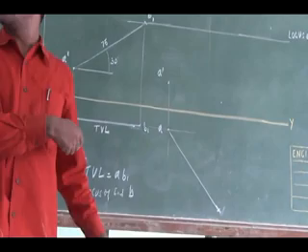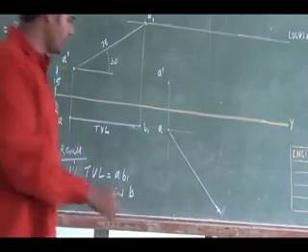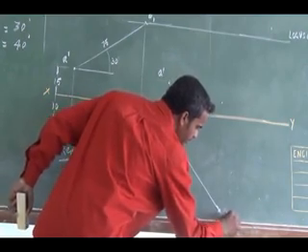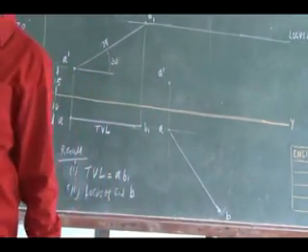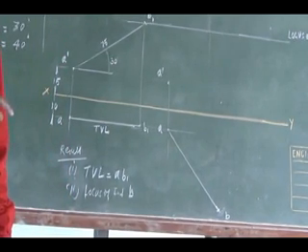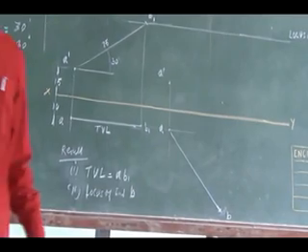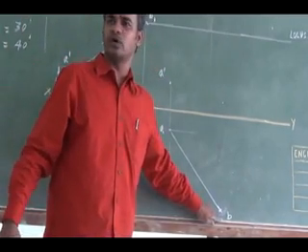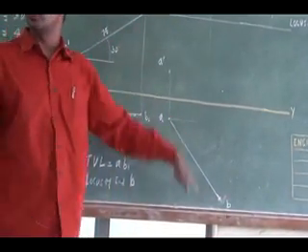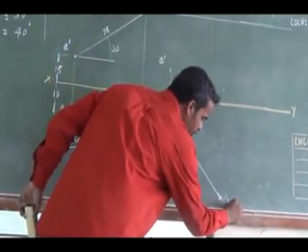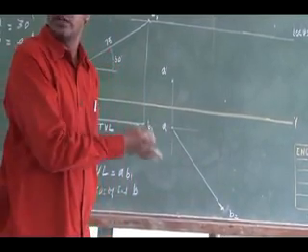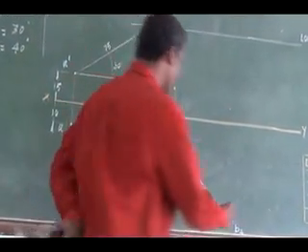No, it is an assumed end location of end B. So I can give a notation of B dash and B. B2 I have to give it. It is the top view. It is an assumed one, already I have given B1, so I can give another one, B2. It is not a front view, it is a top view, so it is B2. So what I can do, I can project this.